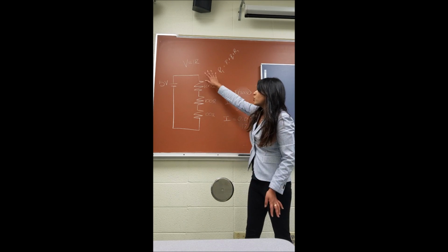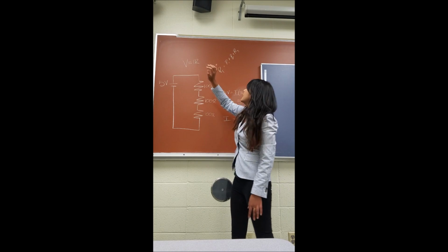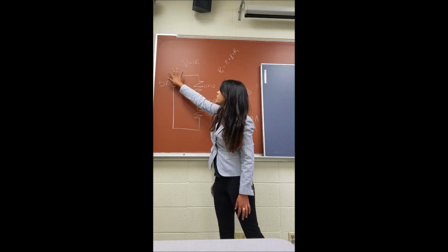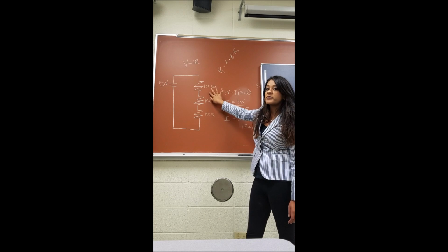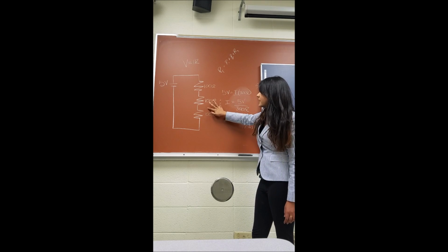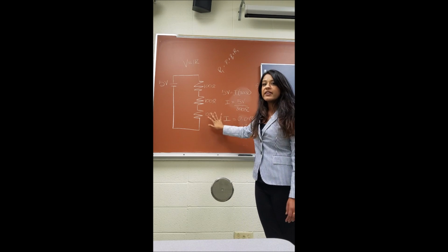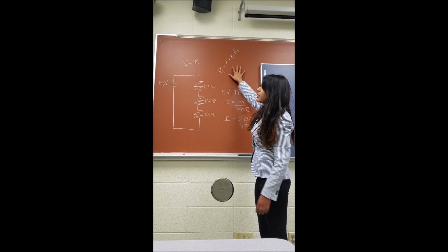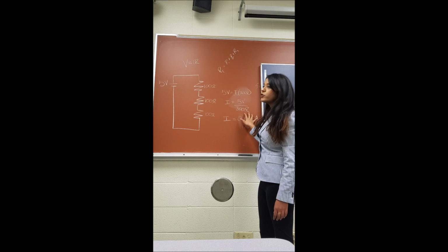We're going to start you off with Ohm's law, which is V equals IR. So now your current starts with a power supply of 5 volts. It's going to move through the circuit this way, coming up to the first resistor at 100 ohms, the second resistor with the same amount of ohms, 100, and the third resistor with 100 ohms as well. When you total all these together, you just have to add them, and we get a total of 300 ohms.